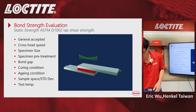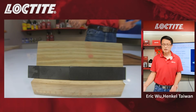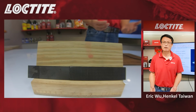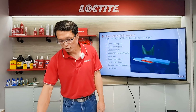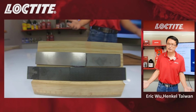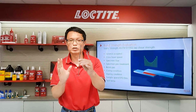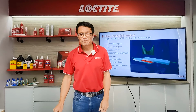We use a specimen that we bond together, like the one in my hand. This is the thing we bond here. You can bond any specimen. We have well-known ASTM specs or ISO standard test methods. You can prepare this specimen very easily, and you can bond steel or aluminum specimens, no matter what kind of material. It's very easy to prepare. And then we put it onto the universal tensile tester to pull from both ends, this end and this end. Later I will show you a video measuring the bond strength at this joint.